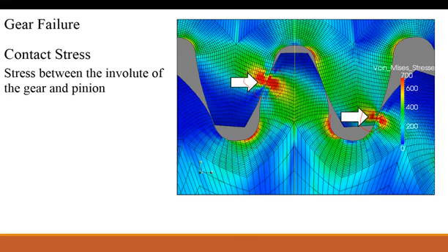Heat treating is very important in gears. So this is where you get a lot of gears where you're actually doing a lot of surface hardness because you want the gear to have a lot of toughness within, but you want it to be very hard at its points of contact.